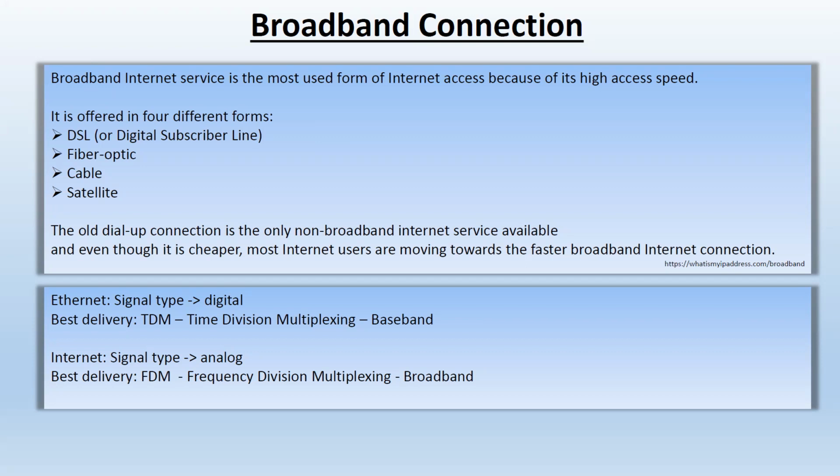But the signal infrastructure was there, and you still wanted to have internet through the same cable. So somebody called and said, look, is it possible to not pay for the phone, but still have the internet signal, the DSL signal, transmitted through the same phone lines? So that was called a dry loop. The voice circuitry, the phone, will be disconnected at the city side, the central office side, but the telephone wire would carry only the DSL signal. So it's called a dry loop.